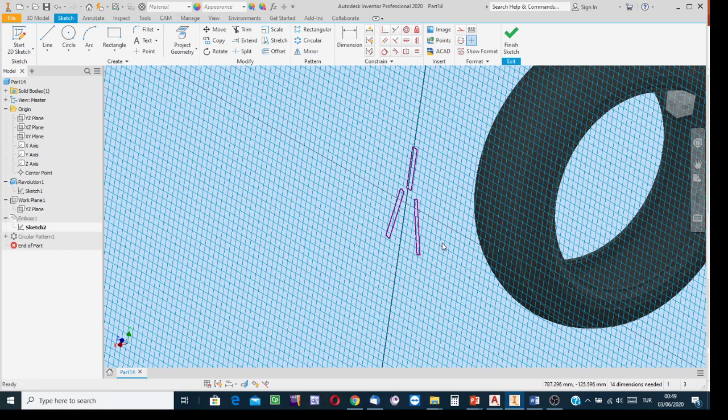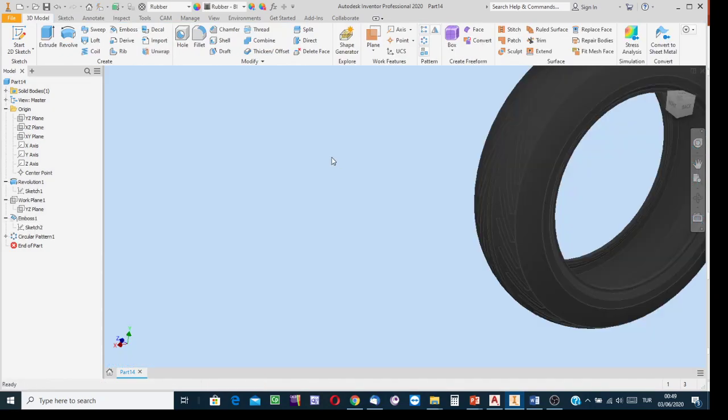It is in this form: a straight one and then inclined ones, which I drafted over the sketch plane in sketch mode, of course with size and shape, inputting the constraints. And after finishing this sketching stage, I apply the embossing process.